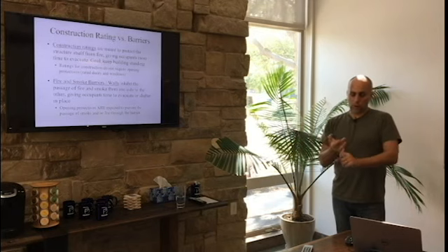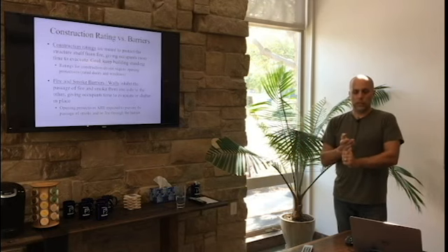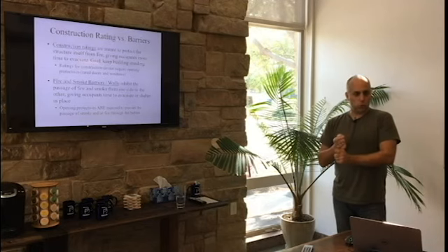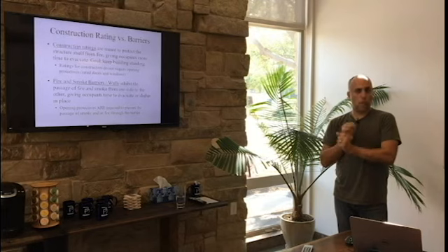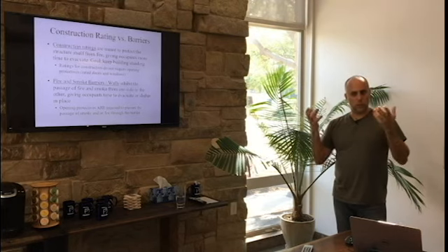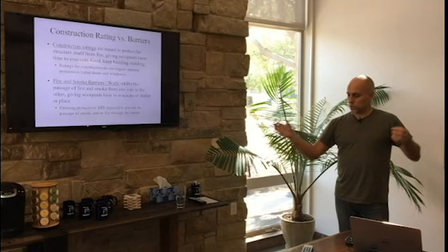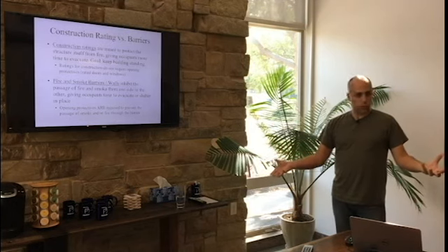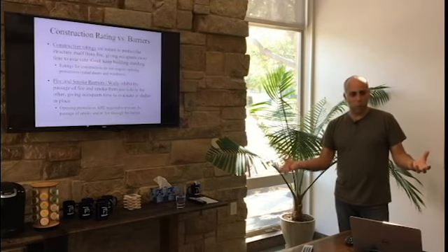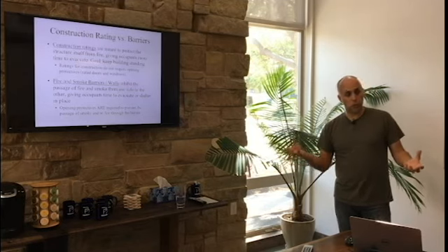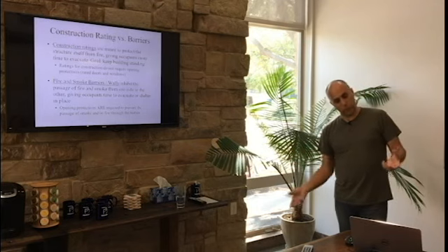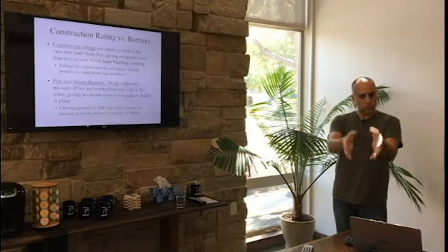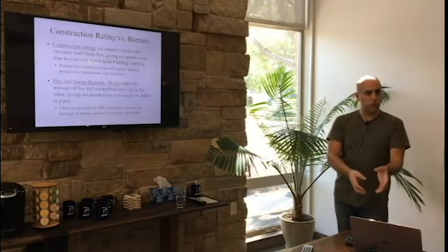So if your bearing walls are required to be 1 hour, you have to keep them from falling apart, i.e. fire cannot get into or affect that structural member for 1 hour. It has to stay standing. Somebody standing on one side of a bearing wall where there's fire on the other side is going to get burned. It has nothing to do with the fact that it's a bearing wall. It's not meant to protect the people directly. It's just meant to protect the building for 1 hour or 2 hours, just to keep it standing, because you can't get out if the building's falling down around you.